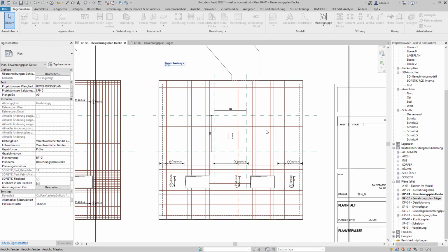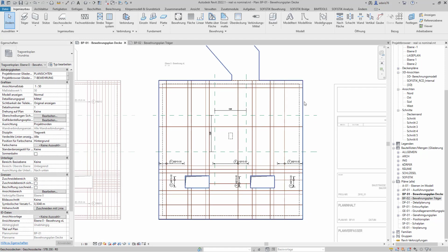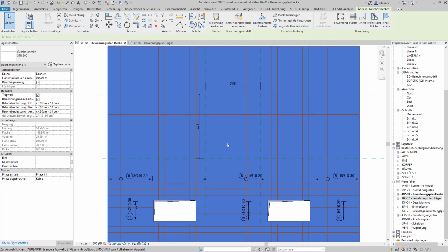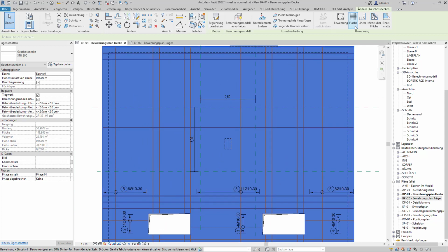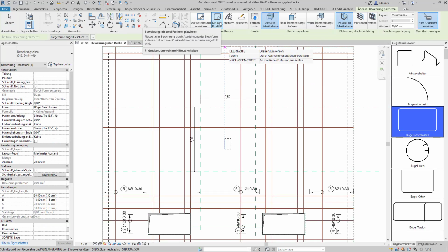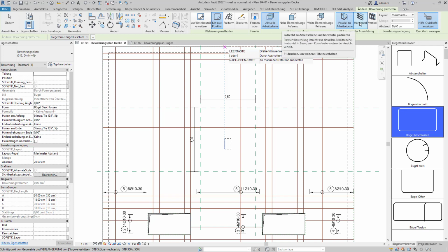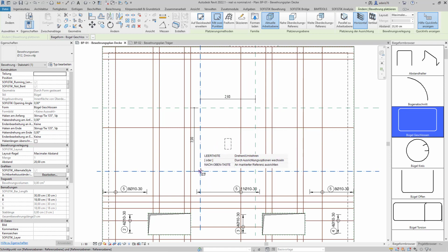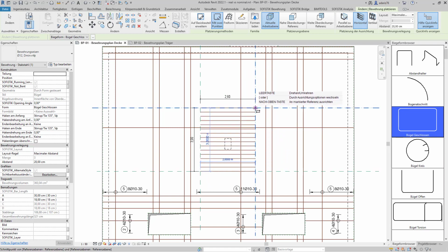It works similarly for supplemental bars on supporting points or line. In this case, I've prepared reference planes that should define the dimensions of the rebars. This can now be used to precisely define the length of the supplementals. The horizontal and vertical option help us to install the bar in the right direction.